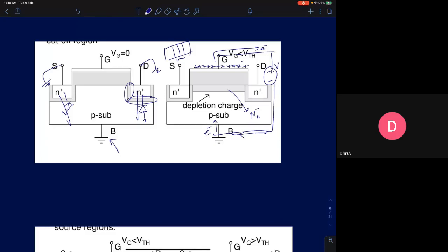Now these electrons which are supplied into the bulk terminal will slowly move towards the surface, because the electric field lines which are penetrating this semiconductor are drawing these electrons closer to the surface. There is an electric field present because of the positive charges on this plate, which is penetrating the semiconductor. Now understand these are electrons. What kind of carriers are they in a p-type semiconductor? Are they minority or majority? In a p-type semiconductor, an electron is a minority carrier.